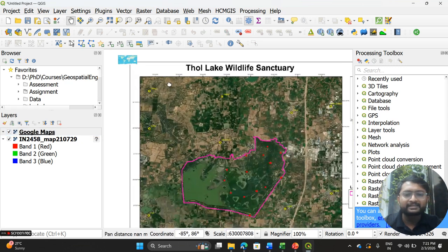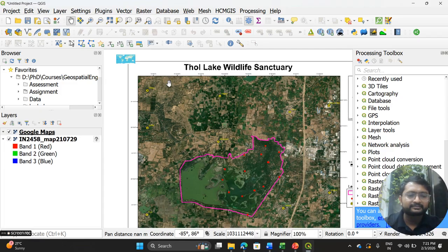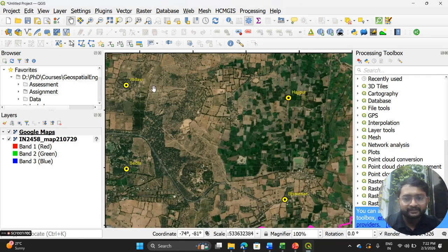So first of all, why is this happening? This thing will actually happen to you when you start working with GIS datasets, so you should be ready with the reasoning. Coordinates. Yeah, the issue is coordinates. Now, what is the issue? This map is not georeferenced. Exactly, the map is not a georeferenced map. It looks like the coordinates are given, but the image is in JPEG format. It is not a georeferenced format.